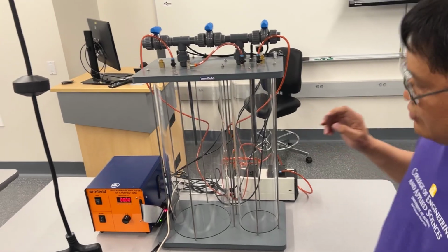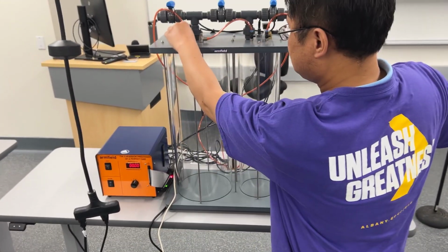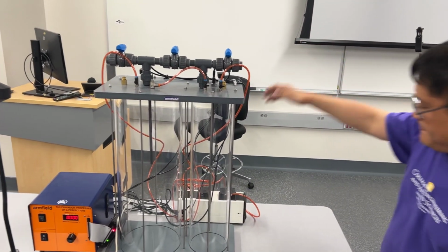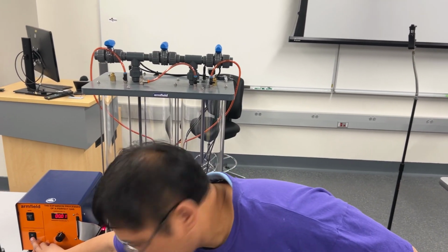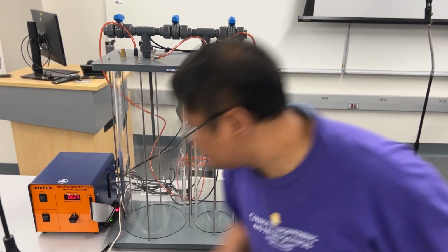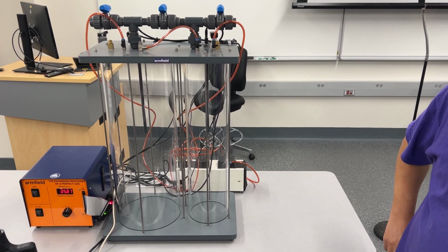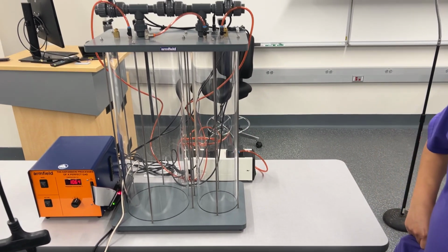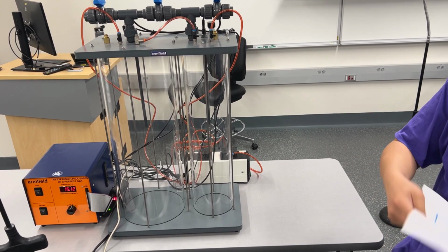And let's see, we just open valve 4. That links to the air pump, and the air pump switch is here. I'll turn it on. So we're pumping air in or out of that tank? Into this tank. Okay, we wait until it gets to about 30 kilonewtons per square meter.